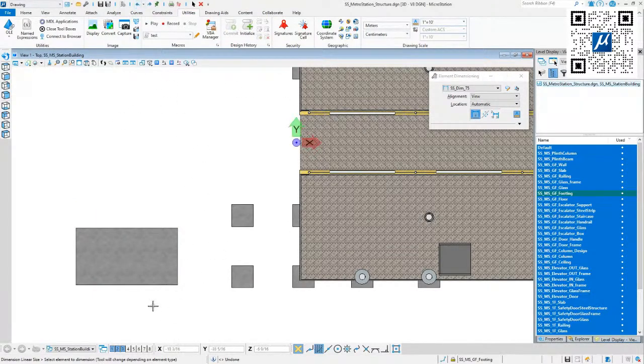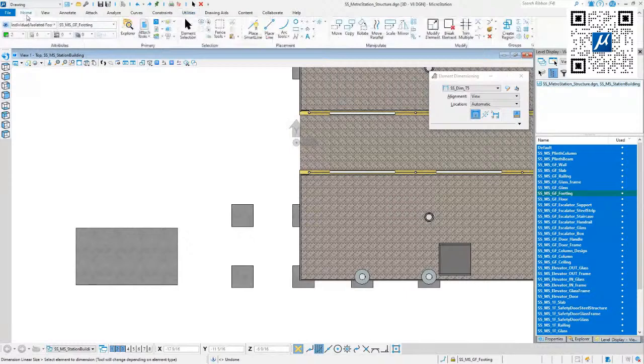Okay, we know about the working units. The working units are part of the MicroStation file, and we know that they can vary precisely. You can go down to 1/1000 of a millimeter, and then you still have a large working area. The next thing, to do an accurate drawing, is that you snap to existing elements. We have to connect the next line, for example. If I draw a line, then I have to connect this line